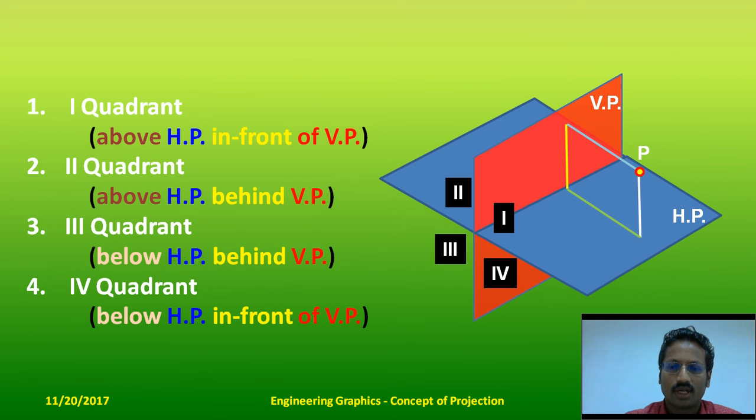You can see when he sees this point, this height is mapping there, and the point is also seen. So P dash is nothing but the image of an object or the projection of the point capital P on the vertical plane, which is called the front view, labeled here with the dash notation. So dash is for front view.